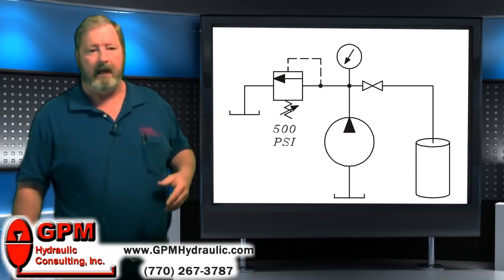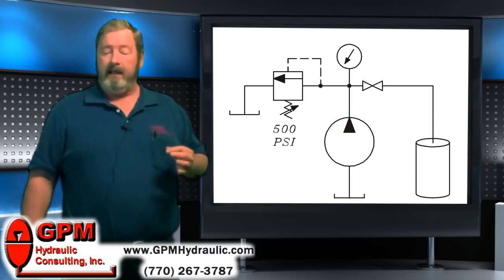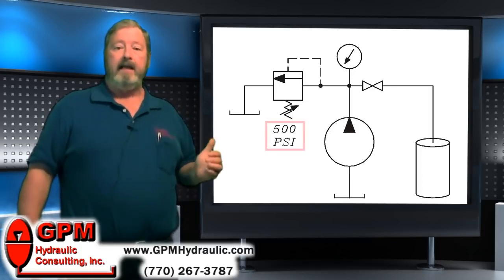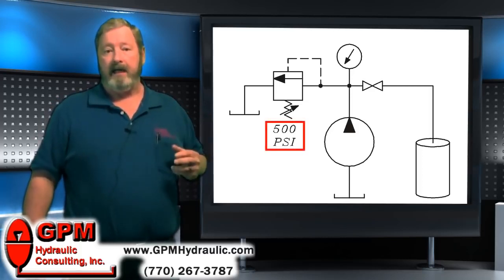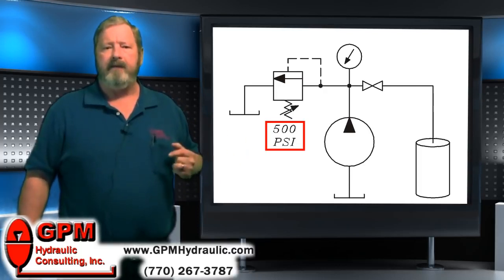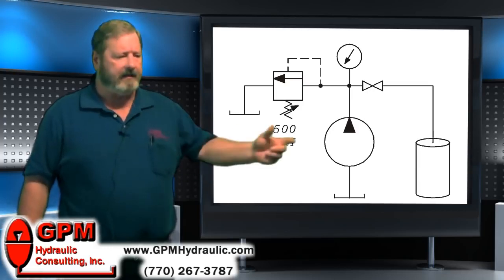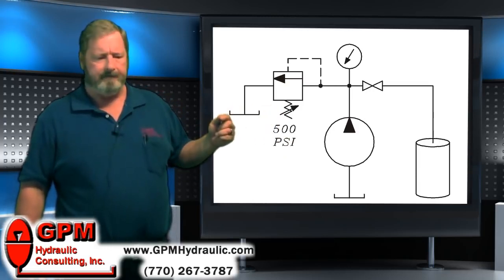You know, who messed with the knob over there? Not me. Well, the last time that not me got hold of this knob, he set it at 500 psi. So in order to go through the relief valve, pressure must build to 500 psi. So that's the resistance in this direction.